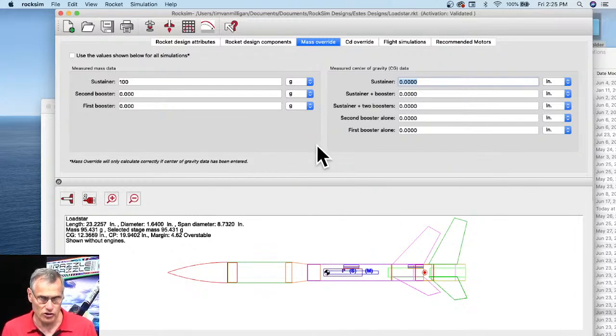I wouldn't use this rocket right here that I'm holding, because it's a different rocket, but you use that sustainer location and you type it in. So then you have your CG in the right spot, and then you can run your simulations, and it'll work really good. But if you want to get a bit more accurate, instead of using that, you have to uncheck this, let RockSim calculate it.